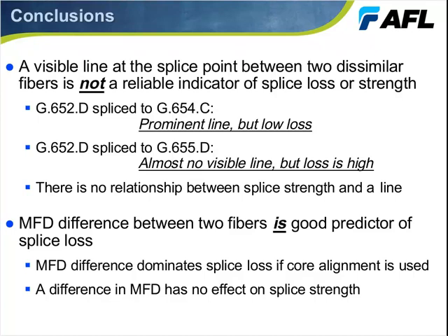Thank you. Next, do bubbles at the splice point occur as a result of splicing dissimilar single mode fibers? Typically no, but unfortunately, due to the alarm threshold in the software of the splicer, it may result in a bubble alarm, which I illustrated earlier in the presentation. So that's why we wanted to present this paper, to kind of differentiate between those two things. But typically the difference between the two fibers itself is not a cause of a bubble.